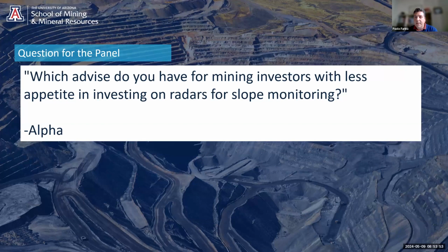So it's important that the design of the slope monitoring program considers what level of hazard we may have at the mine site, and along the life of the open pit, because there could be periods where the height of the wall, the slope angle, the bench face angle, the interramp angle are not that steep, and so probably there is no need of a real-time monitoring system like radar. You could start with a different technology.